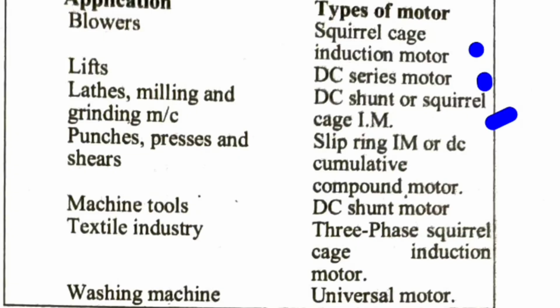Punches, press and shears, slip ring induction motor or DC cumulative compound motor. Machine tools, DC shunt motor. Textile industry, 3-phase squirrel cage induction motor. Washing machine, universal motor.